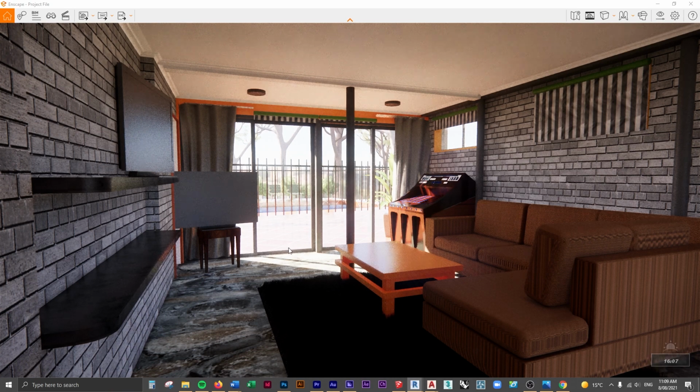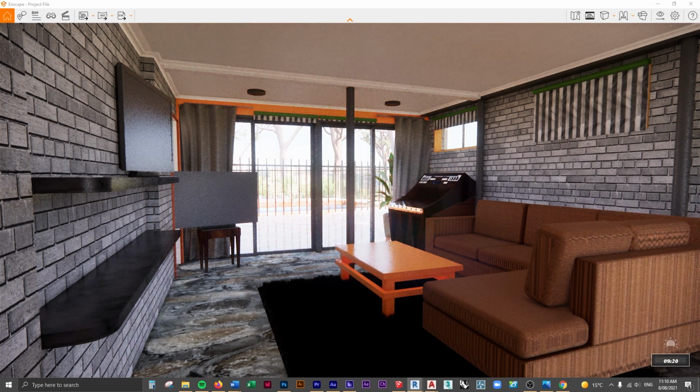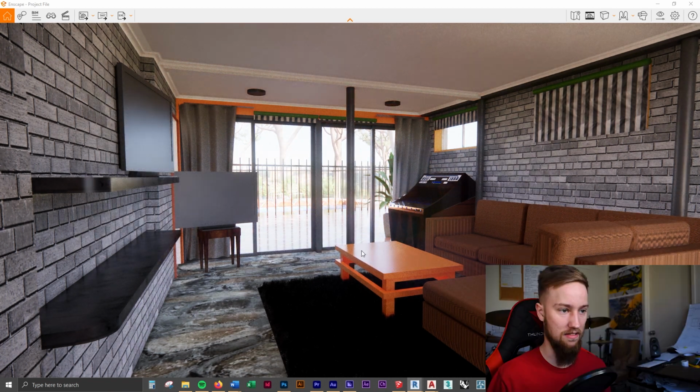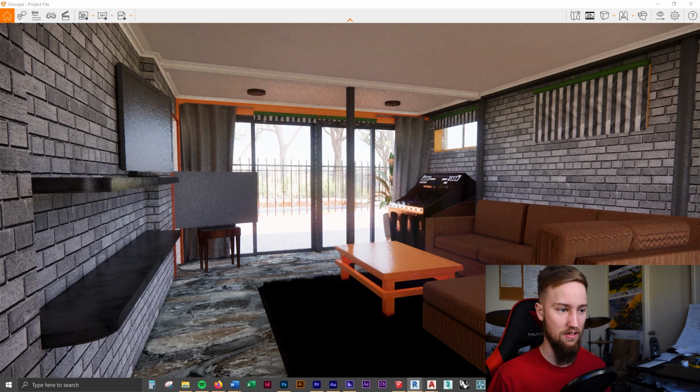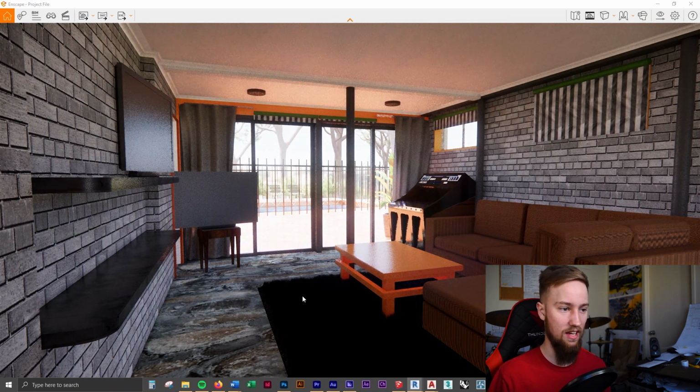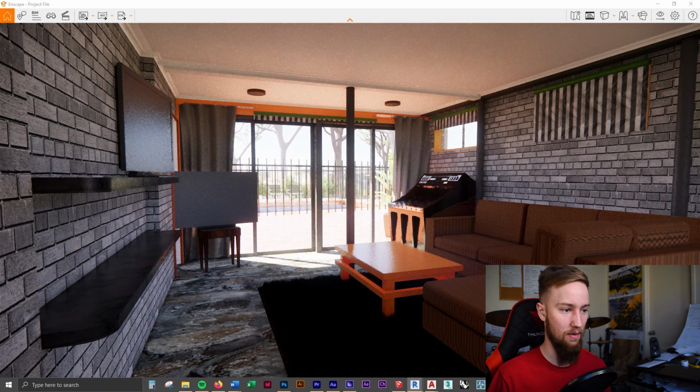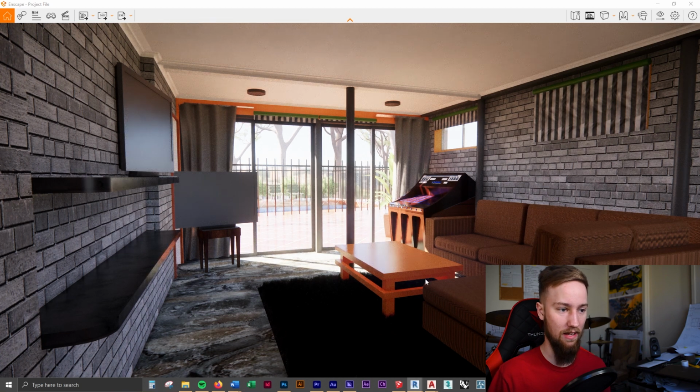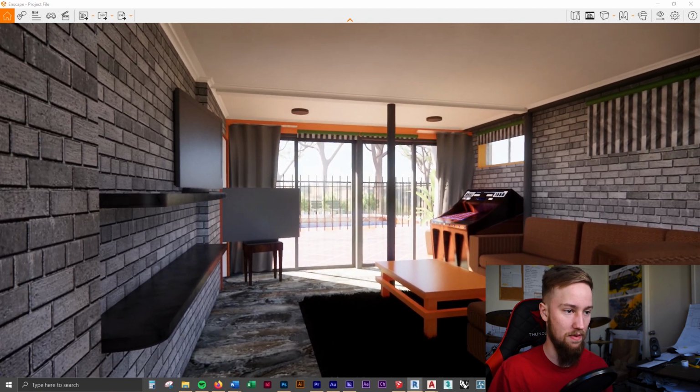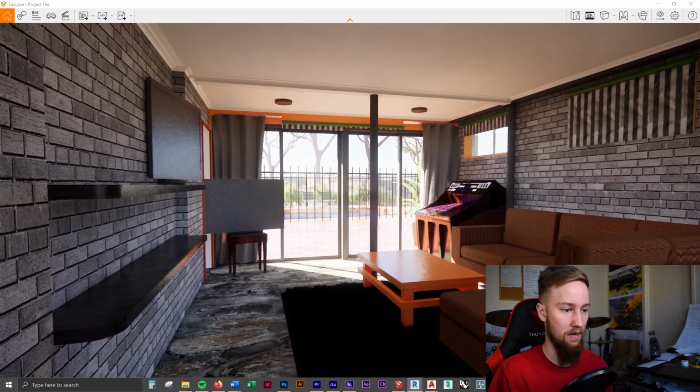At the moment it's about 4 p.m. and you can see the sun's coming in, or you can make it morning time by going over to the other side. Now it's 9 a.m. and the sun is not as strong. What I like to do is set this so that it's just slightly coming in through the building. You might want some light rays coming in from this side, and that looks pretty good, but have a play around with that. Once this is in the right position, we can then hit the render button and do a test render.